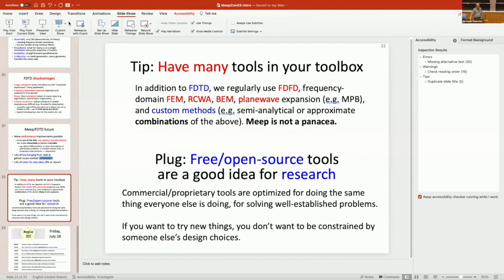The linear materials are a bit easier to validate. For example, if you put in a single-point unit cell that's only one pixel with periodic boundary conditions, it's just a uniform medium, then you can replicate the analytical dispersion relation of that structure, and there's a bunch of other tests. But yeah, you have to do all of these things to test it.